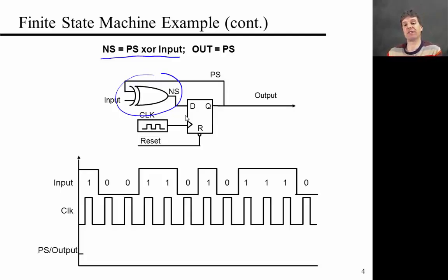Because you only have two states, and then correspondingly they can be encoded by the values 0 and 1, you just need to have a single flip-flop, because the flip-flop can be in one of two states. So that's relatively intuitive. Of course, the flip-flop as an input takes the next state, so the output of the combinational circuit, and then it holds on its output the value of present state, which serves as the input to the combinational circuit. Good.